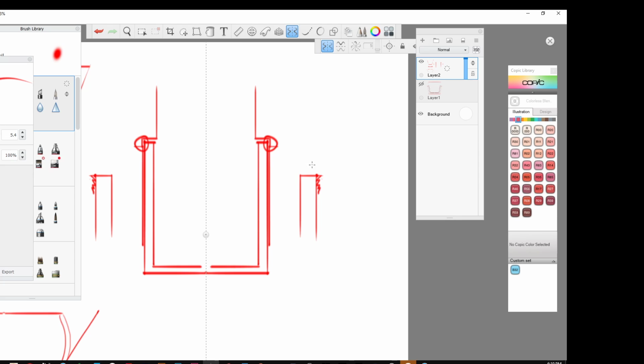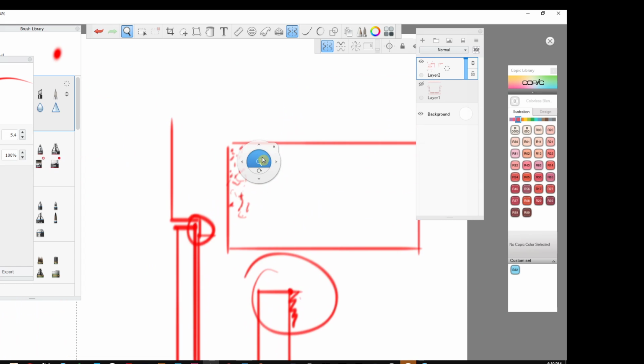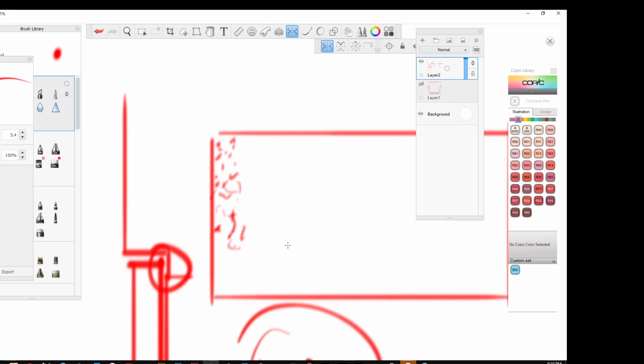Now, not always a big deal, but where it becomes a bigger deal is when you have a texture. So if you have a beautiful texture on your part, so nice texture. What happens is, if you don't have enough draft, when it comes off the tool, even though that's how you designed it with the texture, it scrapes it, and eventually it wears it off to be smooth. So now all of a sudden your part has a whole section that doesn't have texture on it anymore.